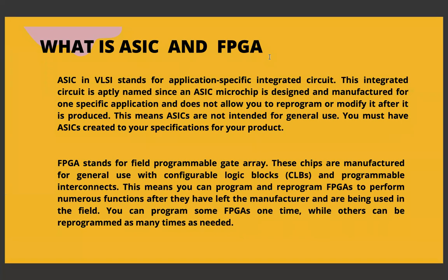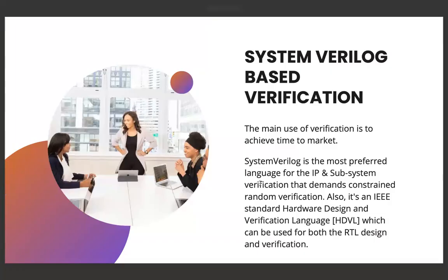Even in the industry, before actually manufacturing an ASIC, you test the design in the FPGA, try to correct all the bugs because it's faster than the simulation. Software is not running, actual hardware is there. You configure those blocks and then you try to program and check it. So we'll also be checking the FPGA architecture, how they are made and different stuff. And we will be studying SystemVerilog based verification and touch upon some of the aspects of UVM as well.